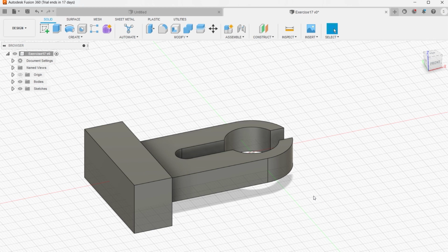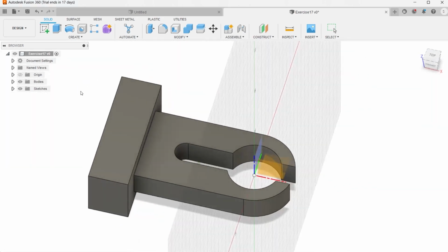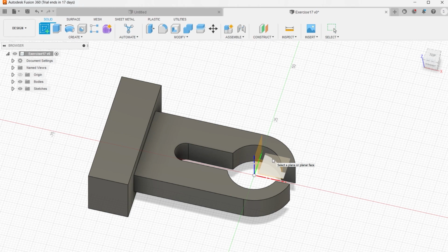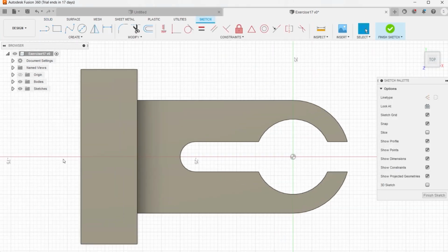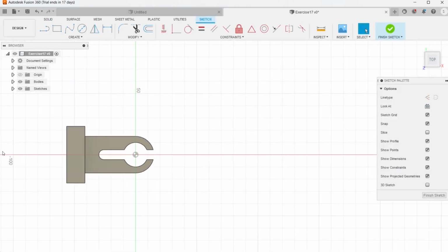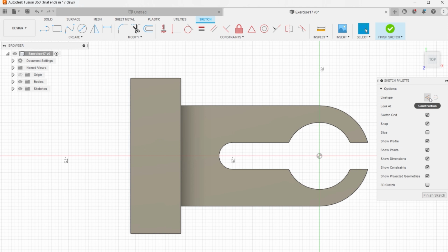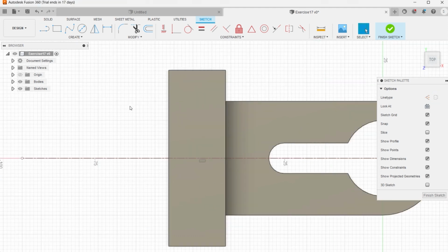Next to that we need to start creating one sketch here, and that to be revolved with respect to the central axis. So let us start sketching from here, and you can select any specific plane. Better to select the top view, and we can start sketching here itself, right? First of all we'll create one central line. Next to that we want to create some arbitrary lines. Let us start from here.